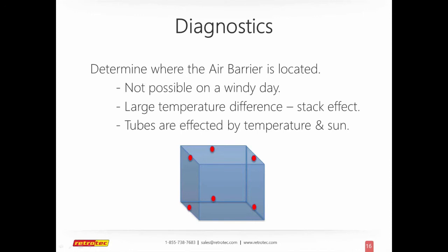It's not possible on a windy day to do some of these types of tests, so you really want to be careful about what's happening outside, because that will affect not just where you put your hose for your reference, but it will actually impact the pressures. Or if you have a large temperature difference, the stack effect can be incredibly significant. You could have a 5, 10, easily 15 Pascal difference depending on the temperature difference or what kind of structure it was.